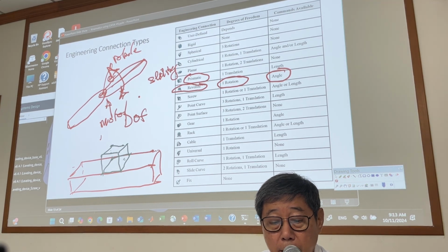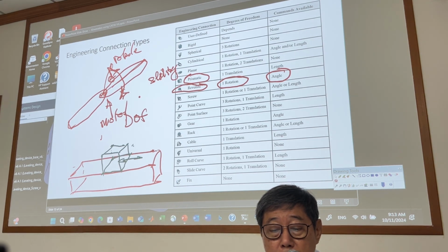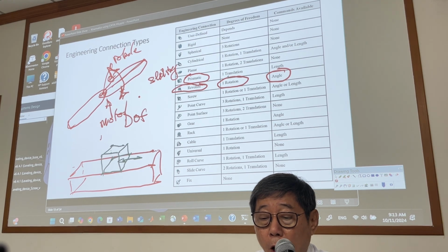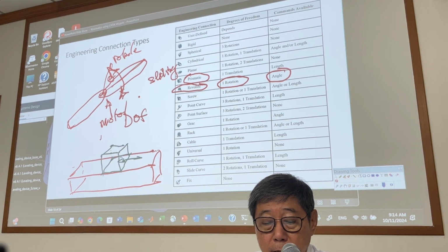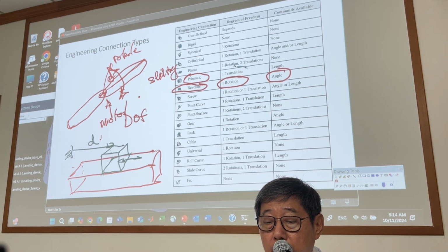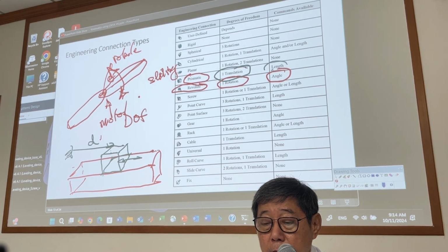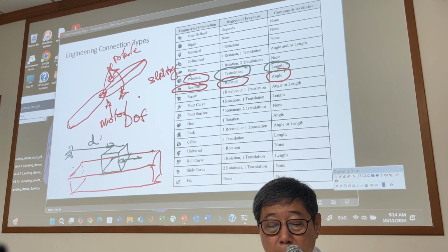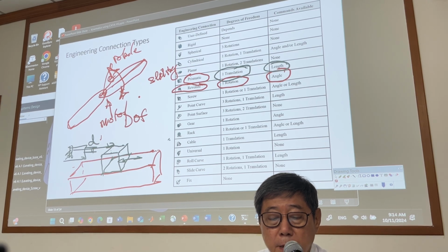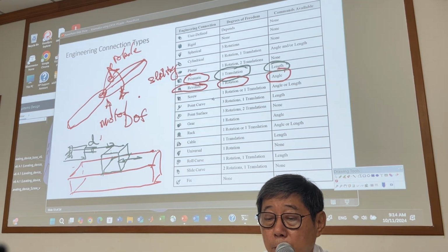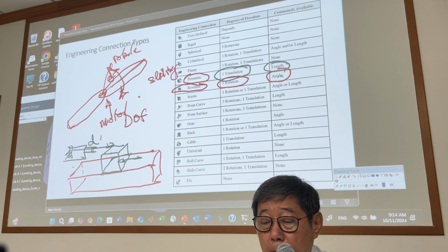And this slides along this joint. Sliding. So this is a prismatic joint. Translate, right? Direction is D. Right? Translate, right? And you can put a linear motor here as well. You can assign a linear motor, right? This one, so that this is going to be moved, right? So it can be commanded anyway, command in terms of length, right? This one.